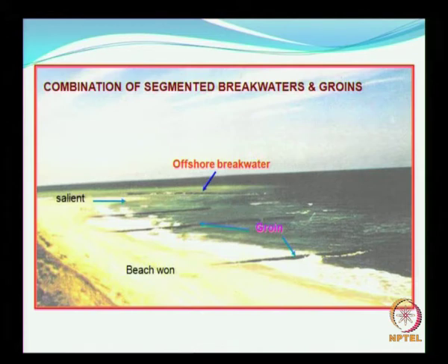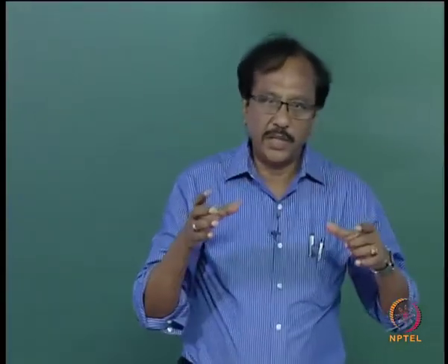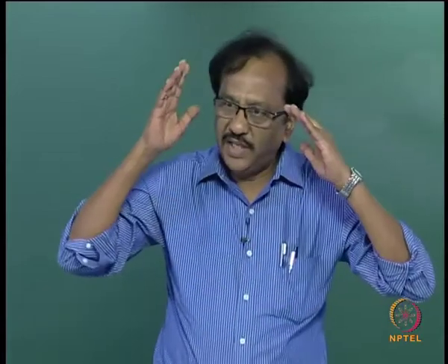For example, you have something like this. So, you have the offshore detached breakwater here with a gap here, and then you have the groins here. So, this will enhance the beach formation. Now, by having an offshore detached breakwater, there is another advantage, because when the waves are coming towards the coast, the presence of the offshore breakwater reduces the incoming incident wave energy.